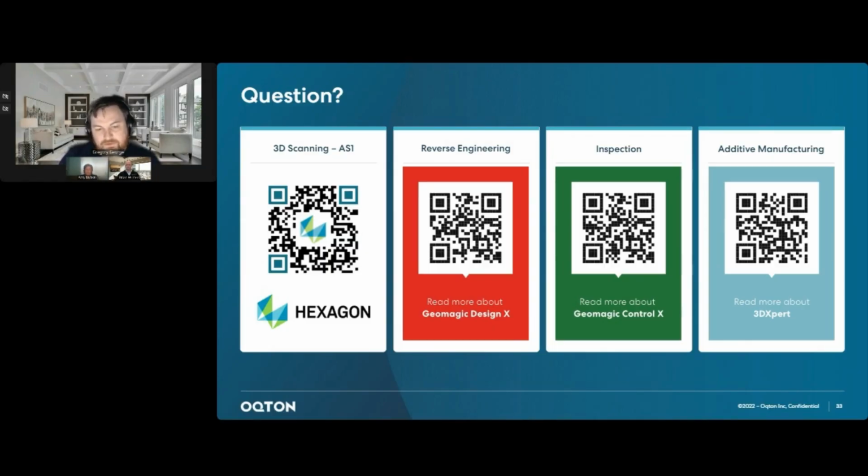And I always say that there are 3 different kinds of automation. You can do one-off ones where I just load up a part and then hit regenerate and it'll spit out a report. We can do batch processing as well, where we just select a folder full of parts and tell it to measure all of those. And then the final one is we have this full automation server option for Control X, where as a scan comes to it, it'll grab it, inspect it, and output the results as well.